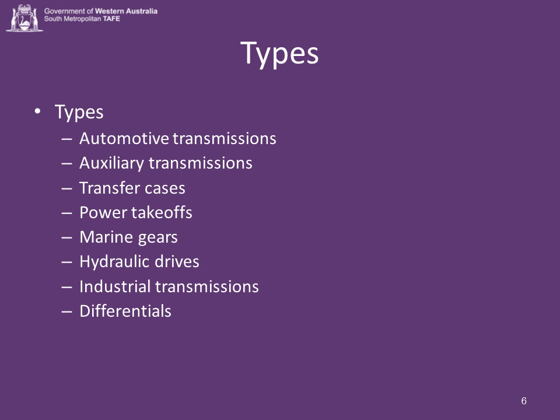Marine gears. Transmission carrying power to the propeller on a marine drive. These differ from other transmissions in that they generally provide single forward and reverse speeds and use a friction-type shifting clutch. Hydraulic drives. Gearboxes connecting power sources and hydraulic pumps in hydrostatic drives. Industrial transmission. This is a broad category applying to any transmission powering machinery other than that described above. Many have integrated power packages, such as electric or hydraulic motors,